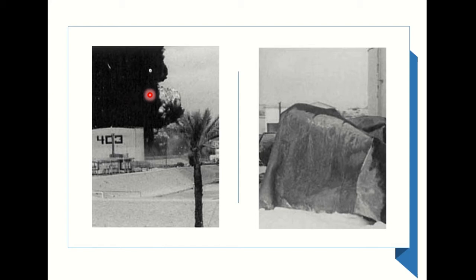From this picture, you can observe that the tank 401, actually behind the tank 403, exploded, and the fixed cone roof ruptured and was thrown into the dike. The fire broke out in the dike and engulfed a great part of the perimeter of the neighboring gas oil tank 402 with 20,000 m3 capacity. The refinery emergency system started to operate in a very short time to cool a few naphtha storage tanks, and the fire was completely put out in 2.5 hours.